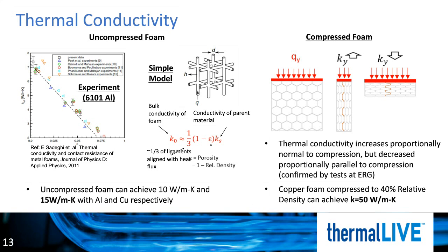This is a common pitfall, especially since normally the heat flux direction is by far the thinnest dimension of the foam core. It is essentially your fin height. It is tempting to just press the foam down to this small thickness, but in fact, you would be shooting yourself in the foot from a thermal performance perspective. Instead, one should compress a larger piece of foam and then slice it to the desired thickness or fin height in the appropriate dimension.